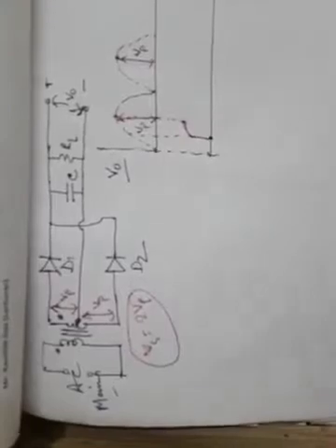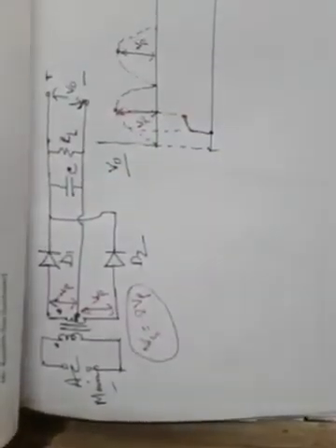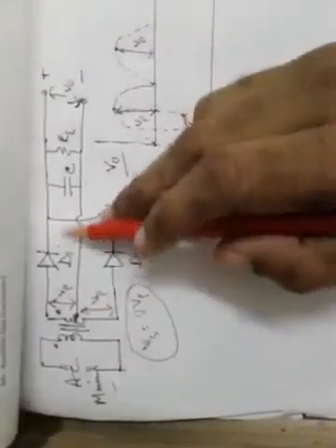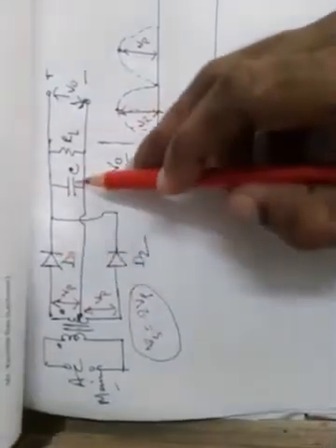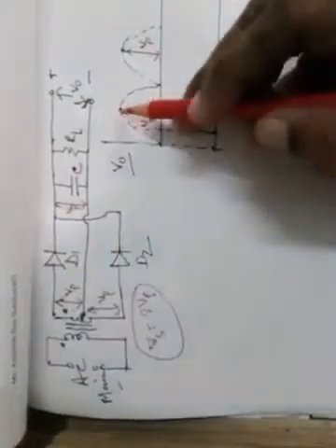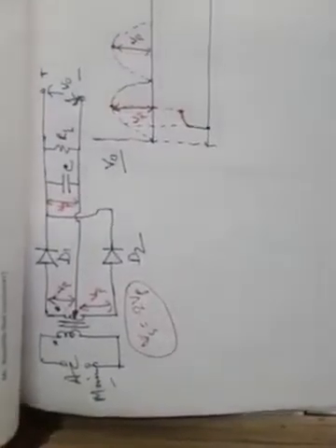So now, up to near about a point Vp, when the capacitor is charged at Vp, by the natural tendency of the input sinusoidal signal, once it starts decreasing, immediately the output side voltage of the diode, which is across this capacitor, will be equal to Vp. But the input side, which was previously at Vp till it reached the peak point, after that, due to its natural course of decrease, will be less positive than the output side voltage, and as a result the diode will be cut off, switched off, or it will be an open circuit.